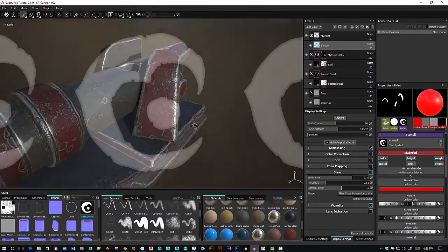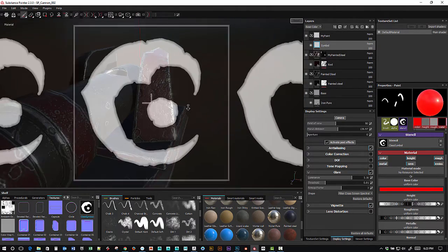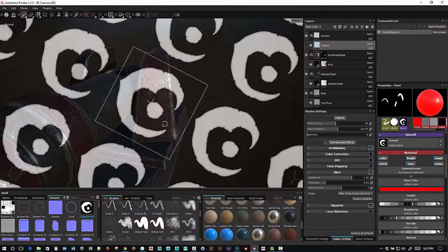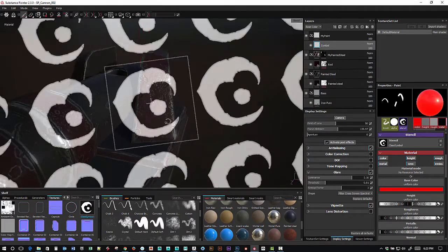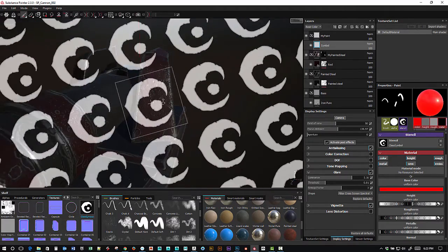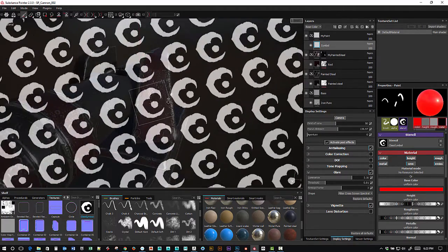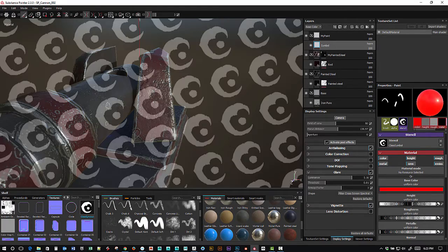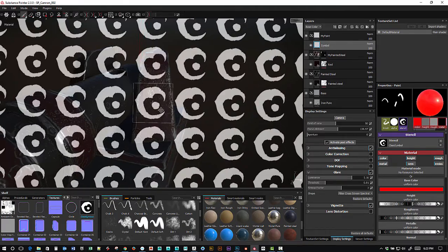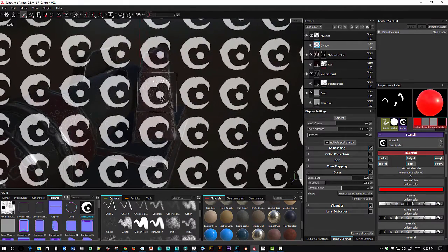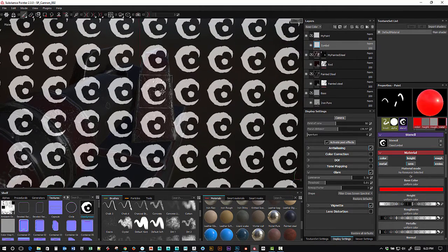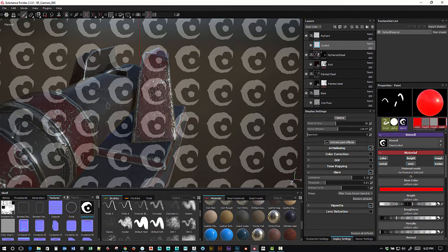And then now you can see I can position this thing. If I hold down S and right click, I can zoom in and out. If I just left click on here, I can rotate. So again, holding down S and right click up and down will scale this thing up and down. S and then clicking with the left click will rotate around, and then S and middle mouse will pan this thing. So I'm going to try to get this thing right about here, like this.